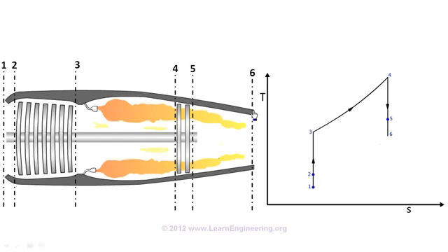It should be noted here that the exit stream never goes back to the inlet condition. At inlet it sucks a fresh stream of air in. So this is an open cycle process. But since both these points have the same pressure, we can assume a pseudo constant pressure process like this, in order to complete the cycle. This cycle is called a Brayton cycle.